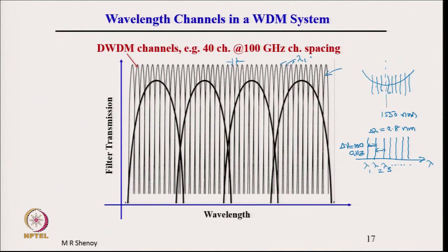And therefore, if I now show this more realistically, please see that every source has a finite line width. So, here we have, this is lambda 1 and this is lambda 2. So, this is the line width of the source, delta lambda of the source, and this separation is delta lambda, the separation is called channel spacing. So, this is called channel spacing, that is spacing between different channels. Every wavelength corresponds to one channel, communication channel, and therefore, the separation between the wavelengths is called channel spacing.